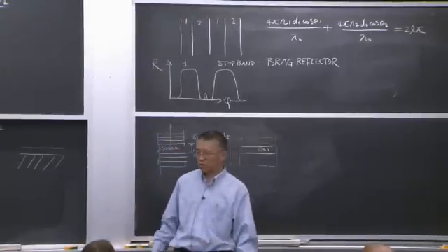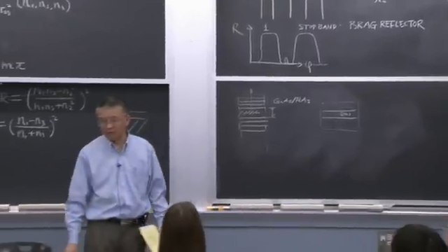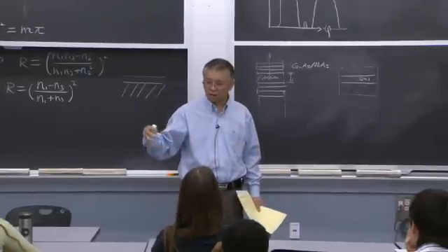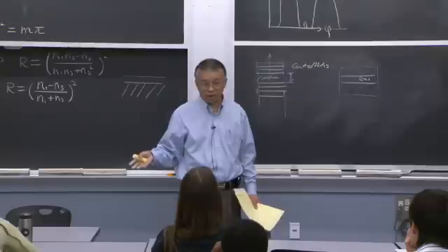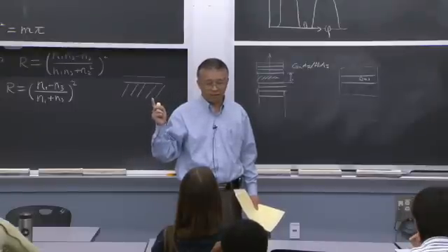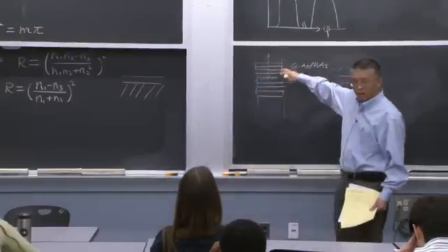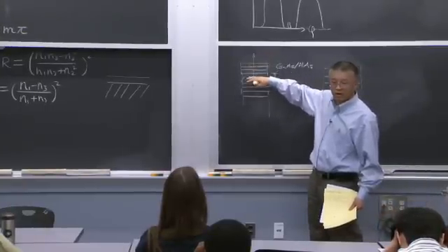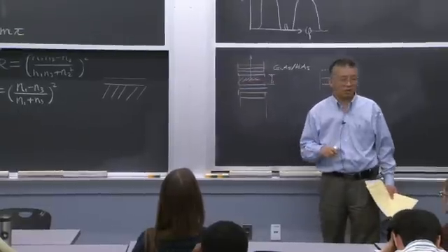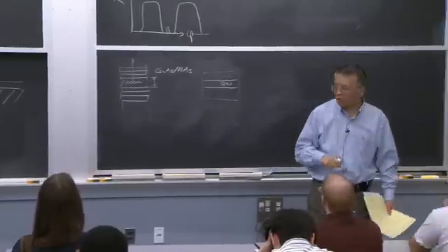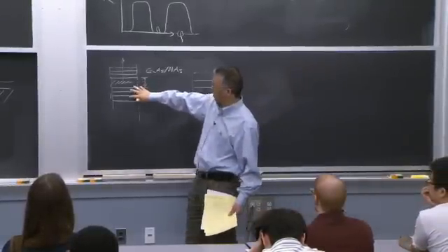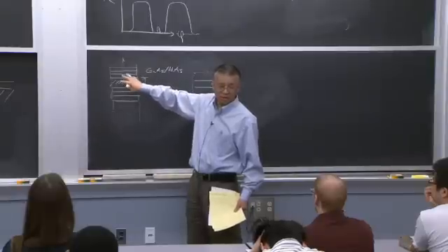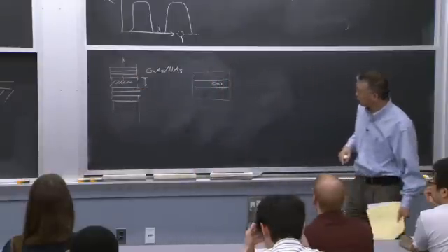When I first did research, I was worried the heat cannot get out, because those VCSELs were conceived in the 1970s, but it was only in the 1990s that they started to be able to sell them, because of the heating issue. When light goes through those multi-layer structures, they have to put a charge going through that structure, and this becomes very electrically resistive. And I started to realize that the heat also has trouble going through those multi-layer structures. So that's what I worked on when I was doing my PhD.